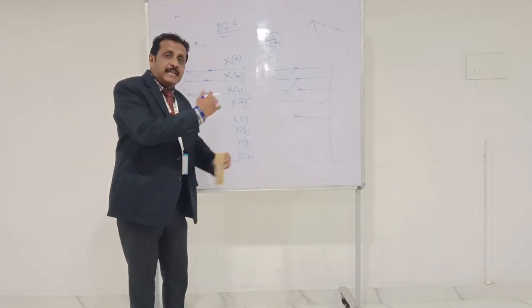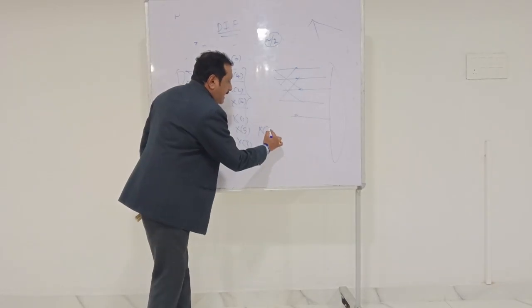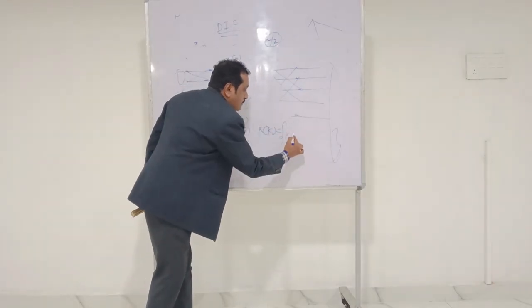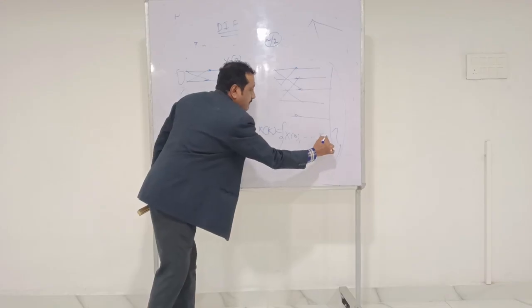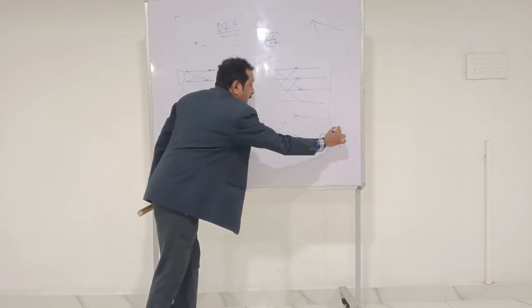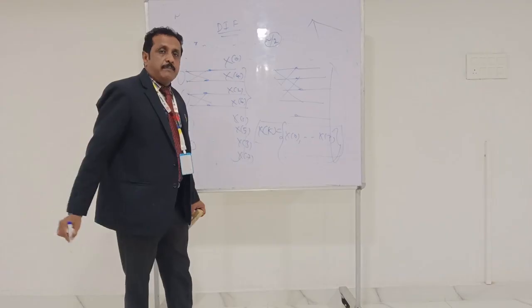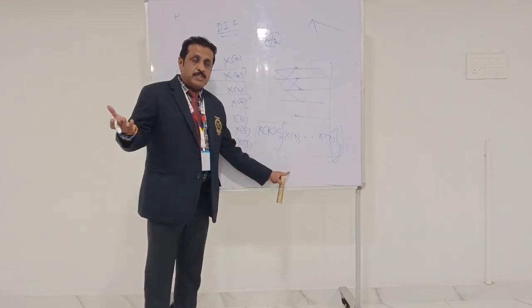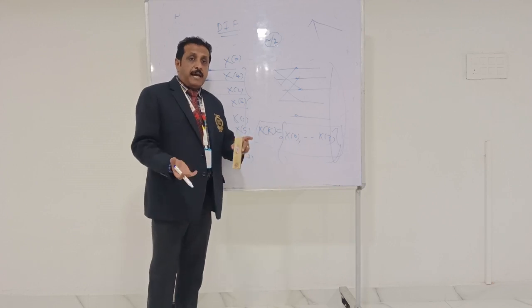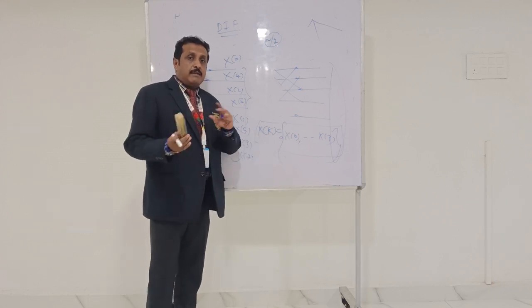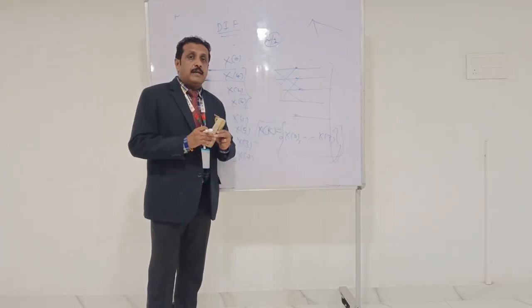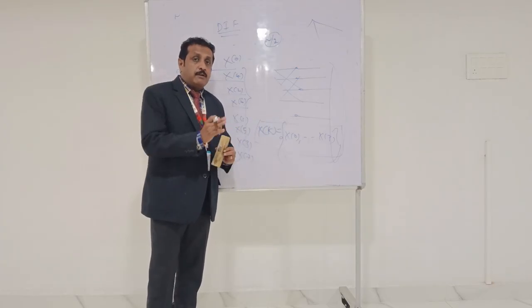After that, we need to make the arrangement. We have to get the final DFT of the discrete time sequence x of 0 to x of 7. That is the way to solve the problem in DIF. Try the same sequence yourselves: you take the same sequence and apply the DIF. Whatever the graph may be, only the procedure will be different.